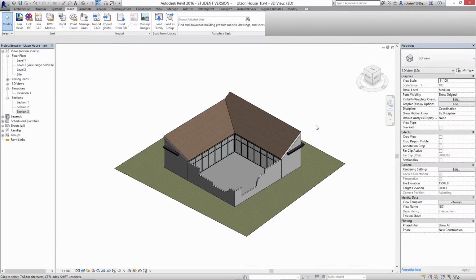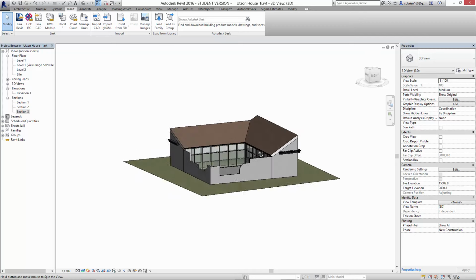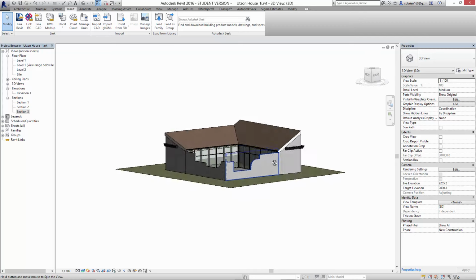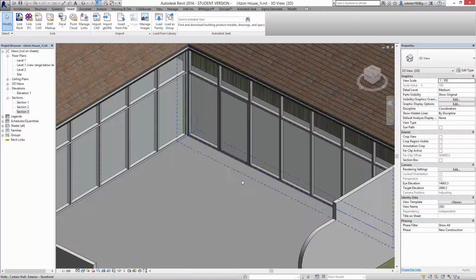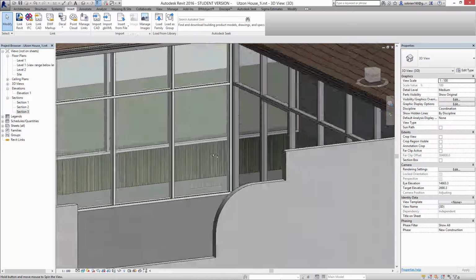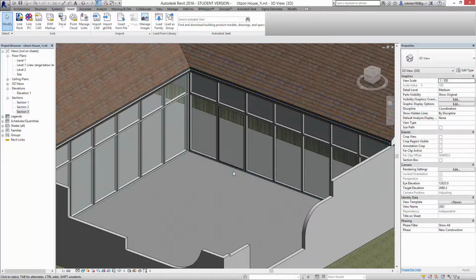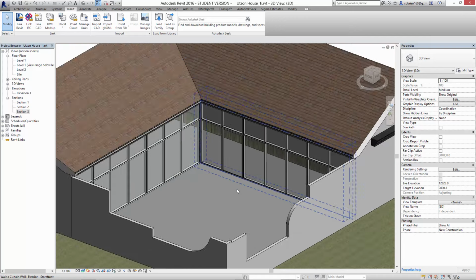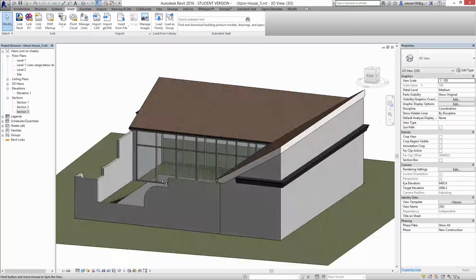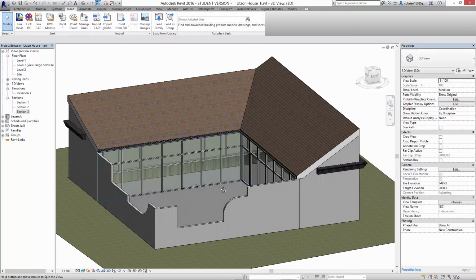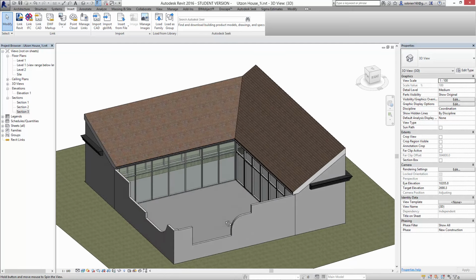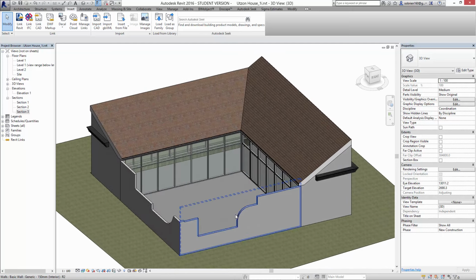On this house here. So we ended up in the last lecture with excavating the soil underneath the house here to a level of minus 900 millimeters. The idea being is that we can put a foundation down there, a floor slab, and then later on we put in another floor at an upper level.